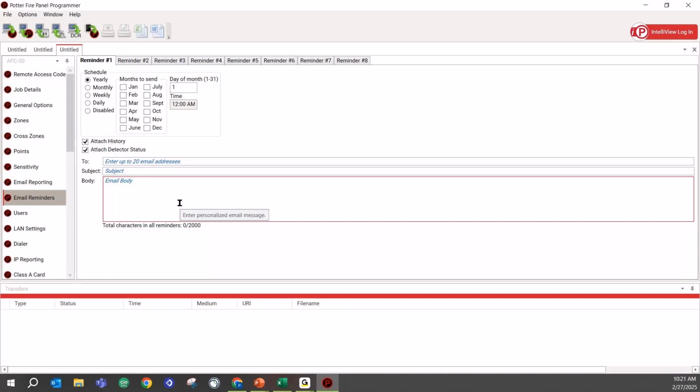The reason I liked both of those is they both gave me good actionable intelligence. Open up that history report. If all 4,000 history events are written in the last 3 months, I've got an incredibly active panel. What's going on? Probably going to send more than one technician. However, if I've got 10 line items written in the last year, I'm not that worried about it. Pretty healthy panel, so we're going to have a pretty easy lift.